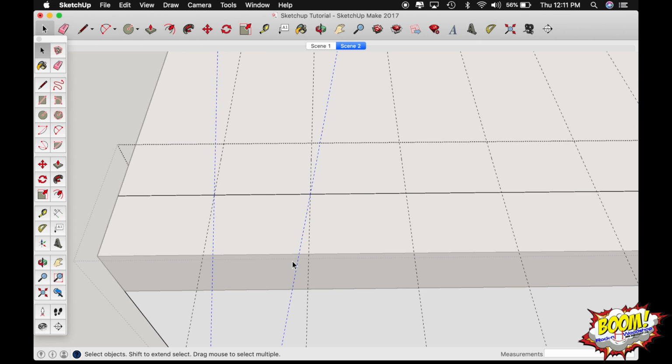All right. Turn on your move function. And we're going to just go up here to this intersection because I need something to reference to. And we're going to copy by hitting Option or, excuse me, not Command, but Control if you are on a Windows computer. And now I can't put it here because I need room for a pin. So we're going to go over here to the next one. And that, as you can see in the bottom right-hand corner of my screen, is 2 inches.